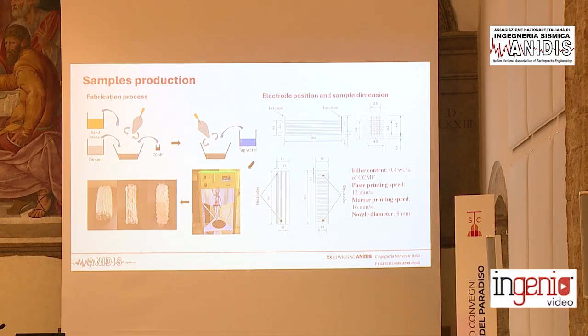The process here was quite similar to the previous one. Mainly, we mixed the dry materials in order to reach a point of homogenization and dispersion. This time we didn't use the hybrid composition, but only the chopped carbon fibers, the long carbon fibers with 6 millimeter length.